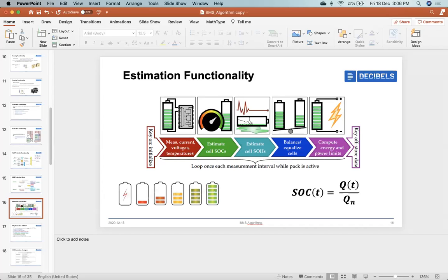But in a general way, yes, when you have sport mode and eco mode and so on, you could send a signal to your BCM, and the BCM would send a signal, depending upon the architecture, either to the BMS or to the motor controls. It's more sensible to send it to the motor controls because the functionality of the controls of the motor is limited there itself. So you don't need to draw more current from the battery pack. Yeah, that's an answer for your question.